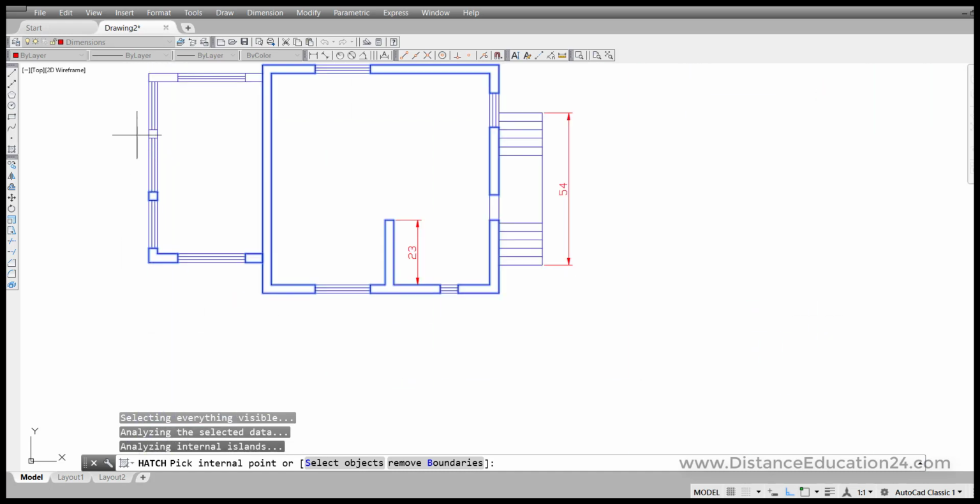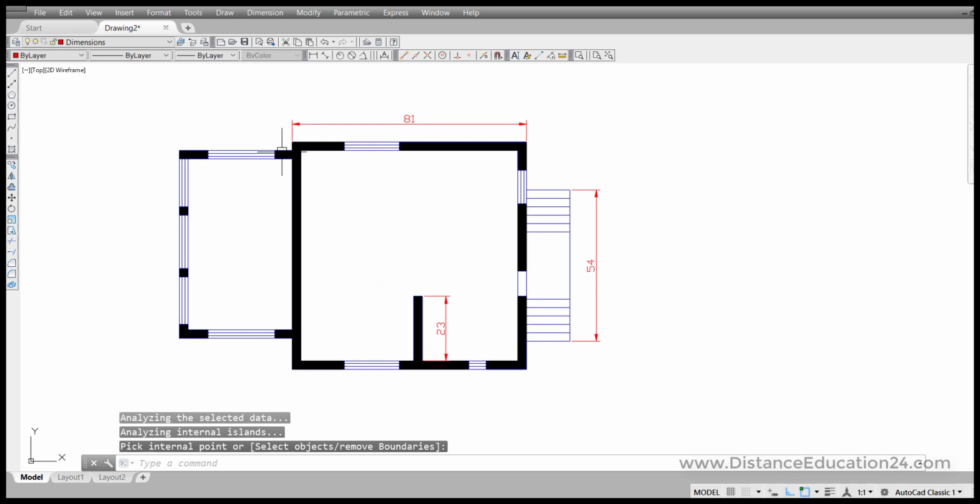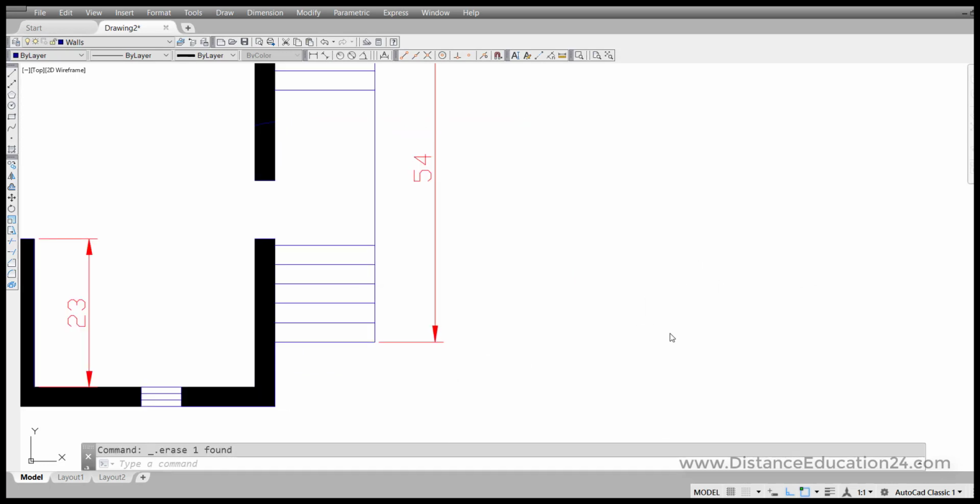we can see, enter, enter. Now we have got a house plan. Let's find out how to draw a door sign here. We have to choose a wall layer. We have to turn our auto mode on, and we have to take line. Let's draw an opened door.